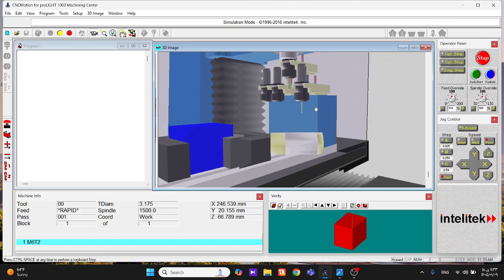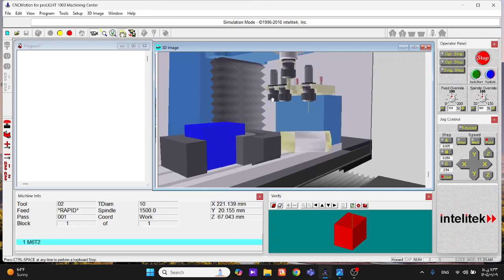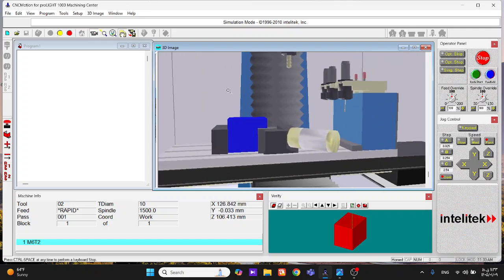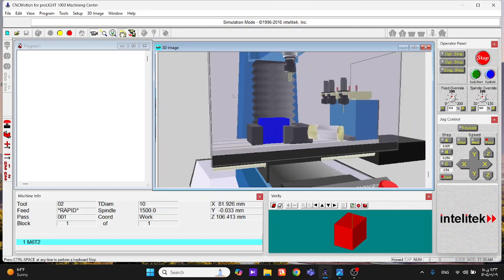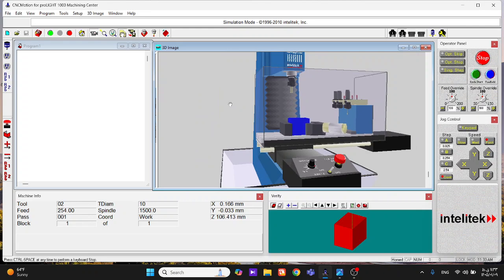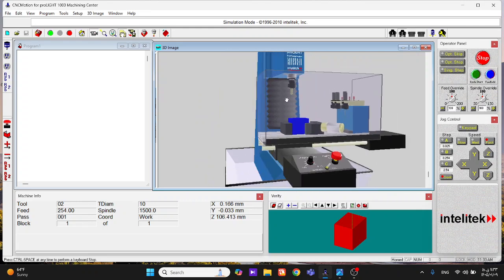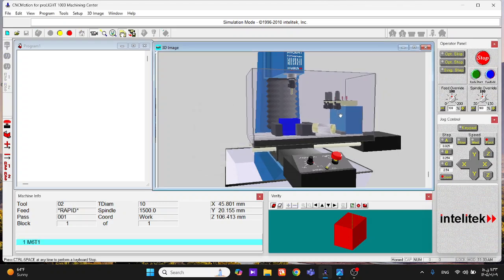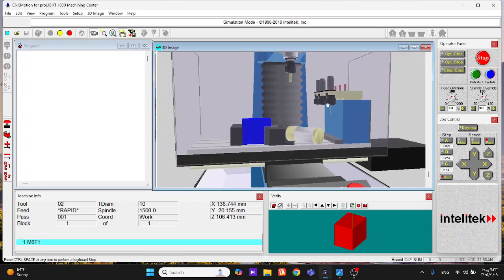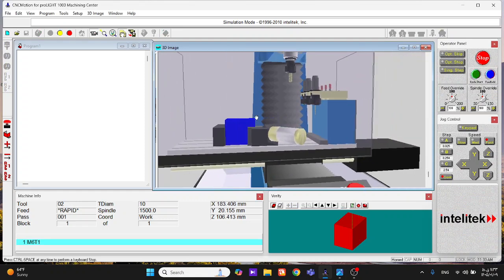first tool to its own position and it will recall the tool from station 2, which for us was our drill. Yes, but because I don't want to start with this tool, I will return back to tool number 1, because first of all we should start with the end mill with the 2 mm, and then we will use the drill to make the holes.